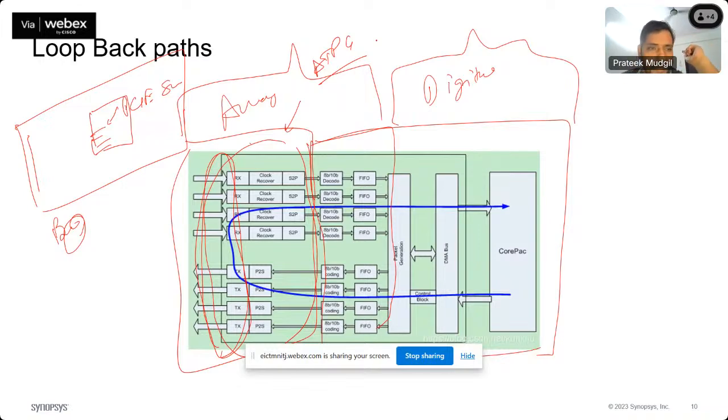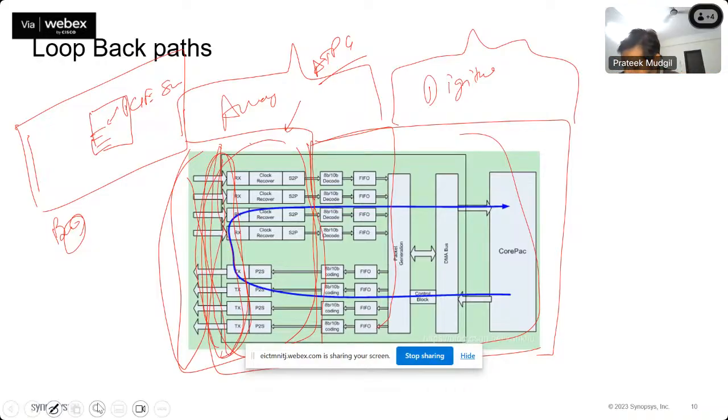So we put the chip on the board and it starts failing. Then we see what can be done, because anything outside is affecting this failure. Our first prediction is that the chip is good, but something at the port level is not good, because we are interacting for the first time with the physical world. Our port impedance and some timing are breaking at this port level. So how can we find out which thing is not working fine?